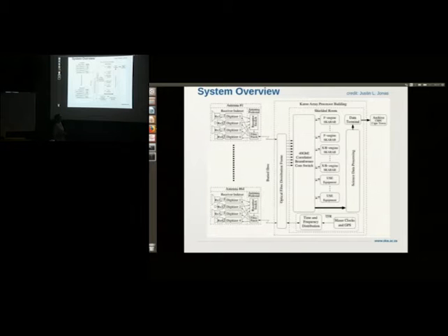There's also user-supplied equipment, and user-supplied equipment can easily integrate with MeerKAT because we make use of multicasting. The following data streams are also available for the user-supplied equipment to subscribe to. So if you've got user equipment, it can subscribe to the raw data coming from the digitizers. It doesn't have to subscribe to the digitizer. It can decide to take the data from the F engine, or if it wants to use the data from the X or the B engine, it can subscribe to that data.